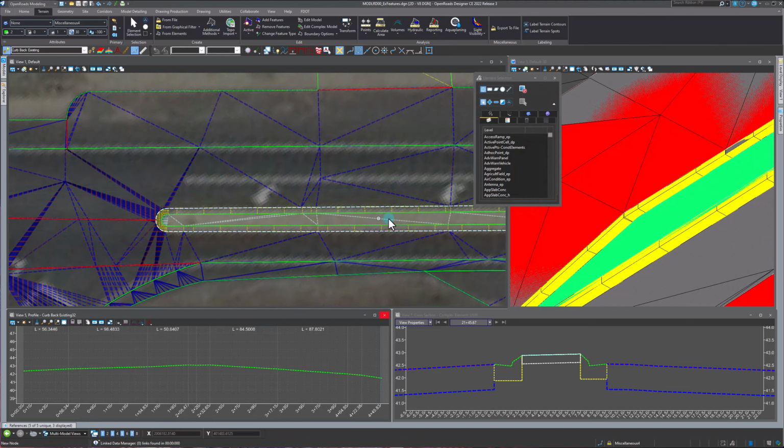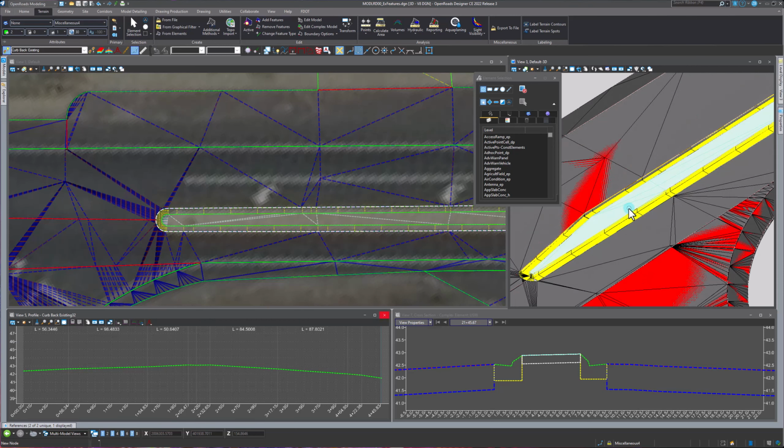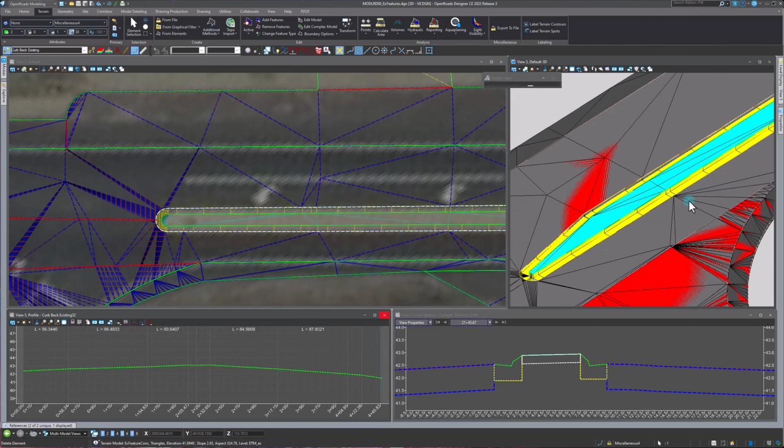I was going to just delete all of this, but I thought it'd be a good chance to show how I would go about deleting some of these surface templates and terrains that we've been creating too. There is a proper way to do this. Odds are you're going to mess up and have to delete stuff. What you want to do is always delete the surface template first. So if you click the surface template, you have the option to delete that template. And then you can come in here and delete the terrain model.